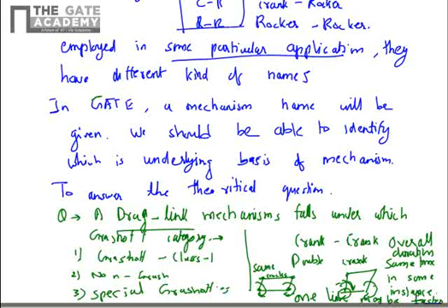So this is called a drag link mechanism. Here one crank is getting dragged by the other crank. That's why it's a double crank mechanism. The drag link is a double crank mechanism, and it is not a parallelogram mechanism. Once you know this, you can recall where you normally see the double crank mechanism which is not a parallelogram. Double crank you see in Grashoff's class 1, where the shortest link is fixed.